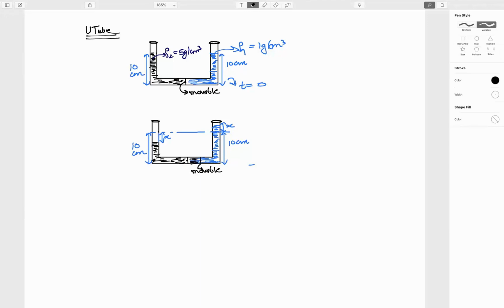So now we need to find x. The general question is what is x? What we do is take this horizontal line and calculate the pressure at this point and this point, because we know that pressure will not change in the horizontal direction. When I say this, you have to think about it: for the current conditions it holds, but there may be a possibility of a change when it is an accelerated fluid, which I have already discussed. So keep those things in mind. Don't listen to me vaguely.